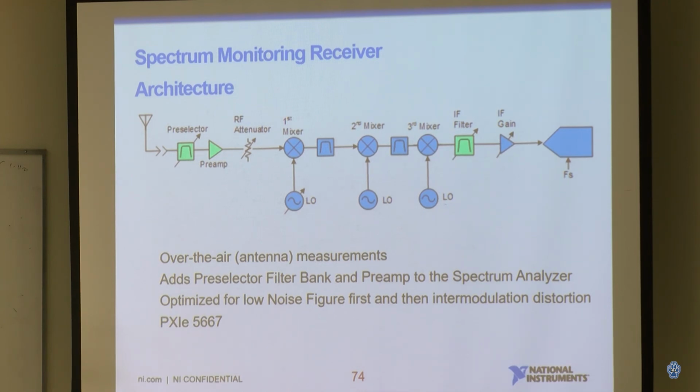So basically it tells you how much noise your system generates on top of your original input signal. So with a lower noise figure, the additional noise on top of your signal analysis is minimal. That means you can recover your original signal and analyze it. So lower noise figure is better. Of course, lower noise figure components mean more expensive and more challenging.